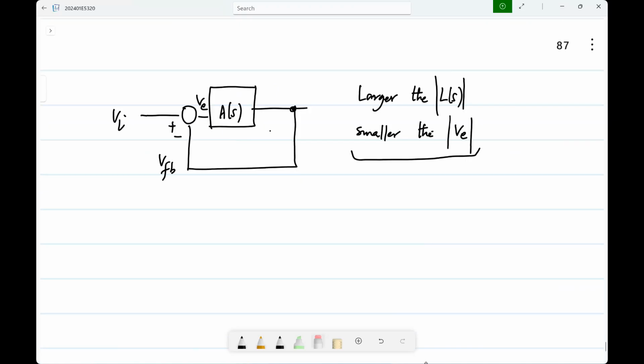That problem is not in exactly the same form, but there also you would have seen that the nonlinear product would be suppressed by the loop gain. So the smaller the error, the lower the nonlinearity, because you are driving the nonlinear stages with a smaller signal.